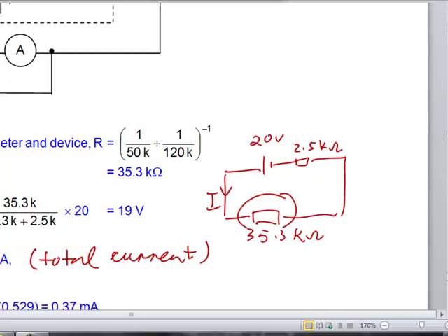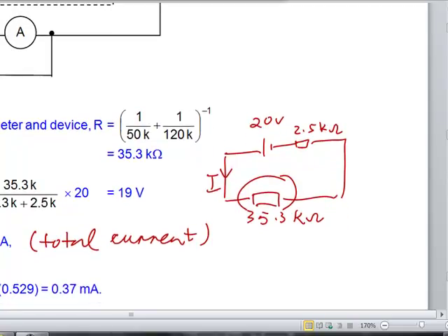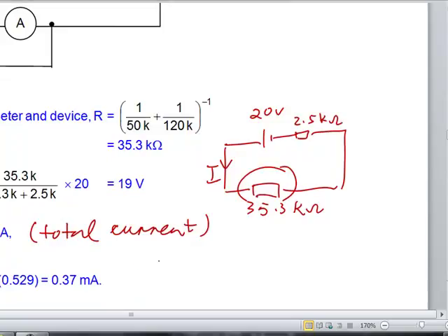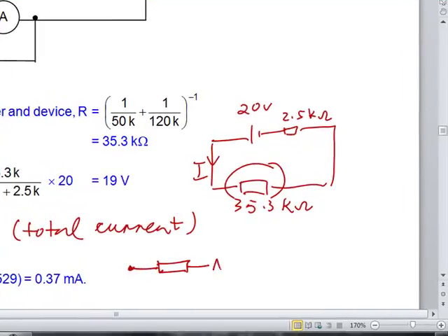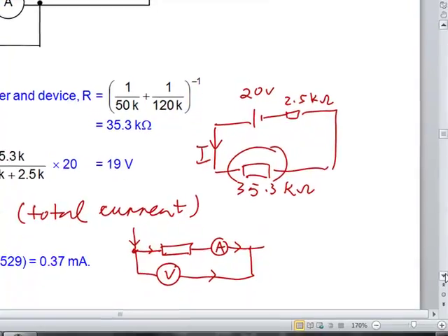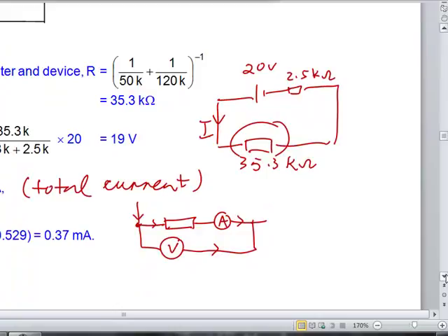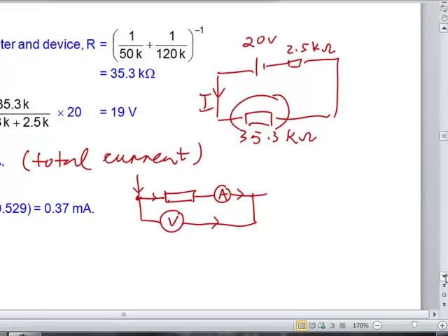the battery. But at the junction where the voltmeter connects to the resistor, the current actually splits into two paths. One path goes into the resistor, the other path goes in through the voltmeter, then they recombine back. Okay, but they have a common potential. So the way to calculate it is actually using the ratio of the resistance.